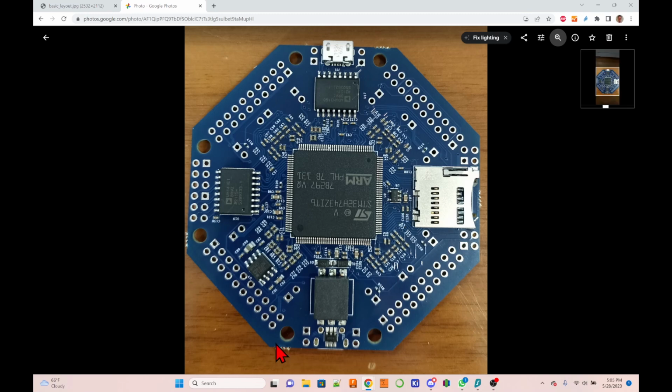And then I think you only need pin headers on those 4 positions, but while you're at it, I would say just solder all of the positions that there are. If you count them, 1, 2, 3, 4, 5, 6, 7, 8, 9, 10, 11 locations where there is a position for 2 pin headers.